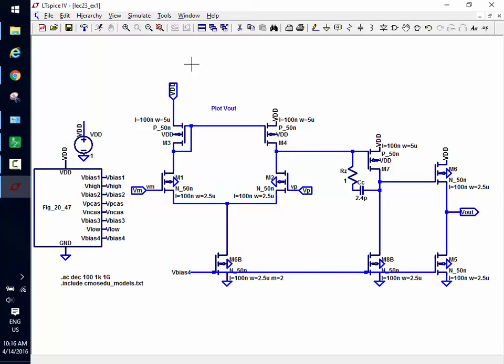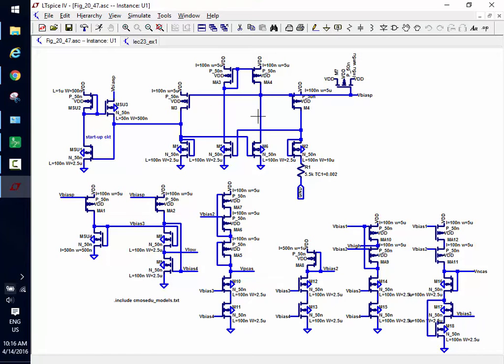Okay, so in this op amp, do I need this elaborate bias circuit? I do not. I only have one bias voltage, right? So I could just get away with the beta multiplier and none of this other stuff here, right? I could get rid of all of this except for the beta multiplier. Does everybody see that? Questions?